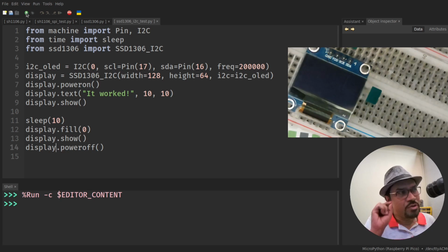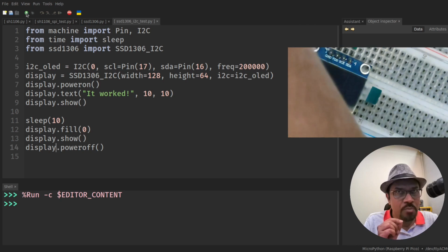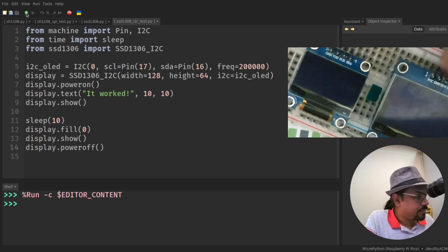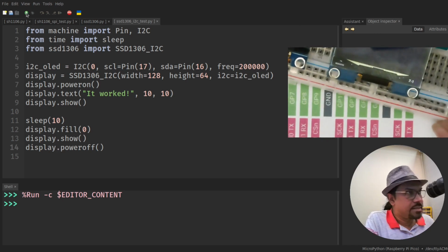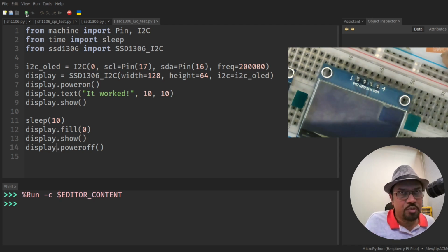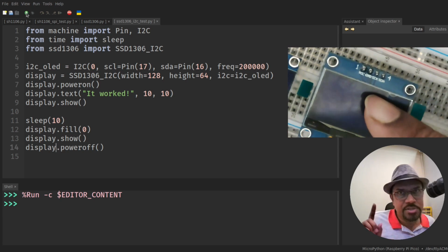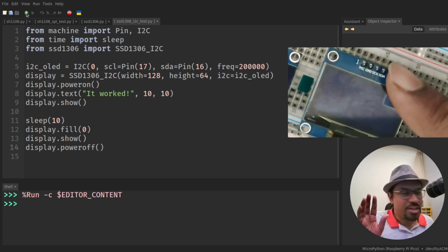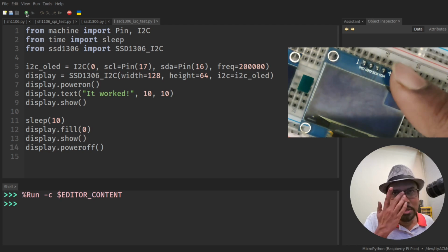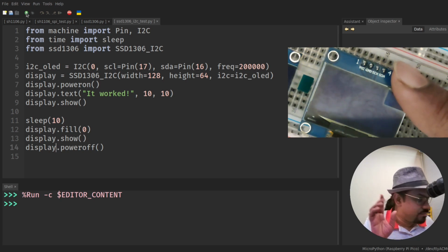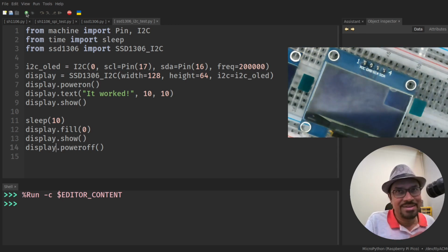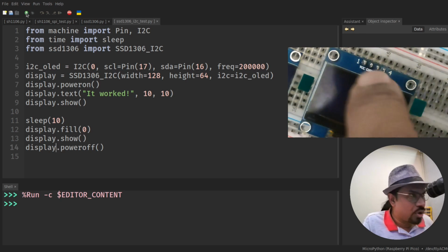The final one I want to show you is there's another 4-pin display which I have, which happens to be a 1.3 inch 4-pin display. This one, right? You can see this right here. This 1.3 inch 4-pin display. But this is based on an SH1106, but using an I2C protocol. A small variation, right? Earlier, we used the SH1106 with the SPI interface on the WaveShare boards, but you might also get a 4-pin display, which is using an I2C interface, but the chip is based on SH1106. So I'm going to show you how to use this one.